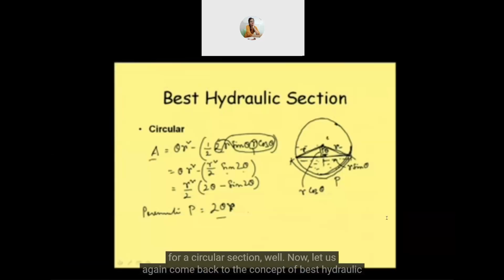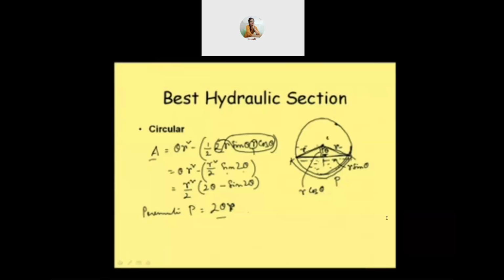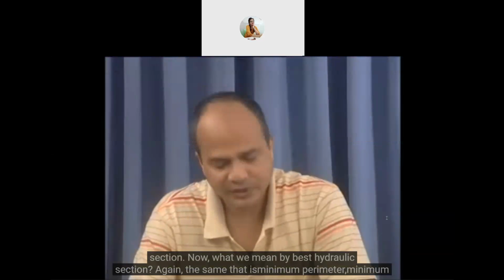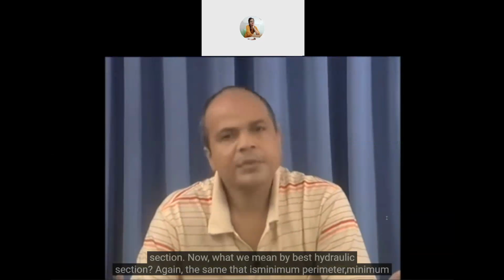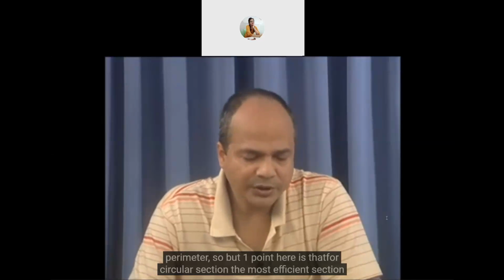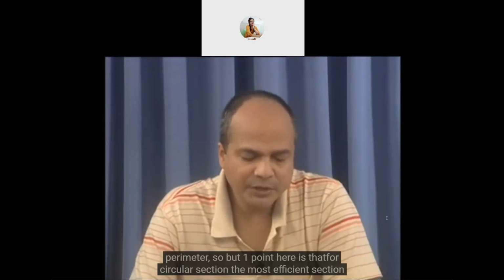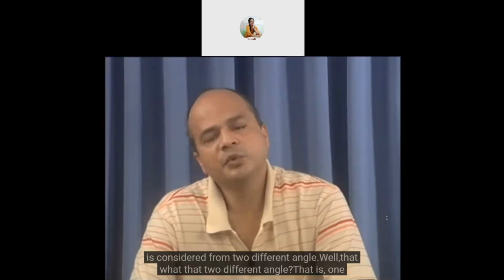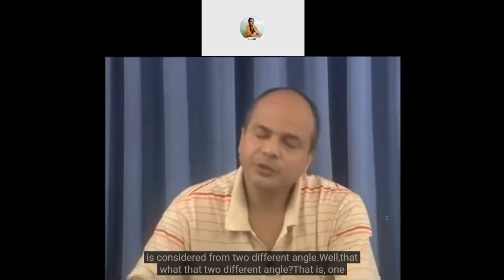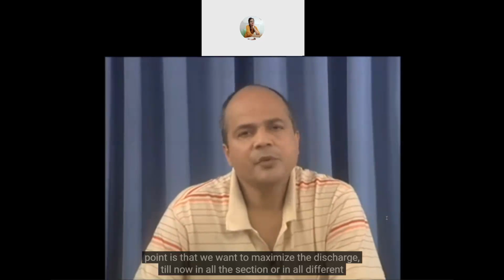Now let us again come back to the concept of best hydraulic section. What we mean by best hydraulic section is again the same thing, that is minimum perimeter. But one point here is that for a circular section, the most efficient section is considered from two different angles. What are those two different angles? One point is that we want to maximize the discharge.